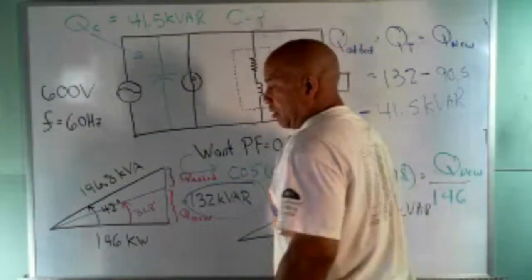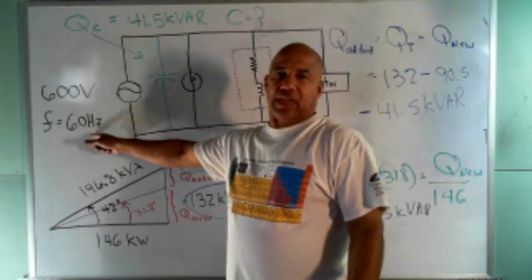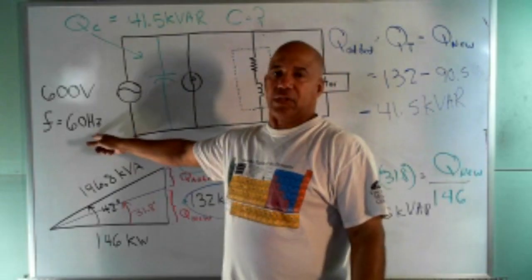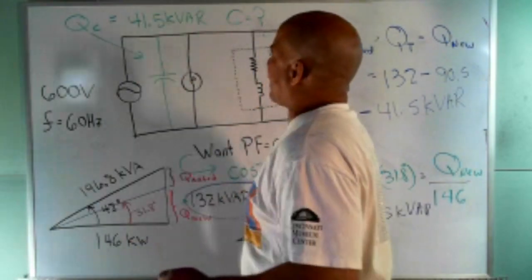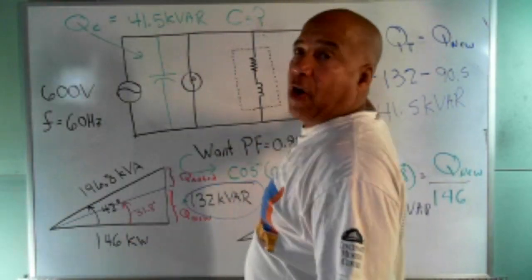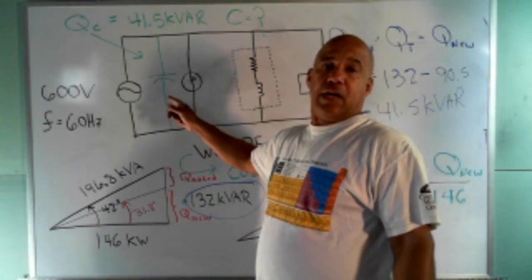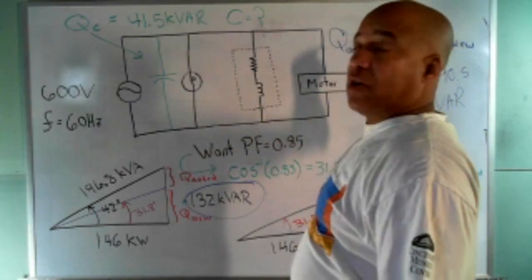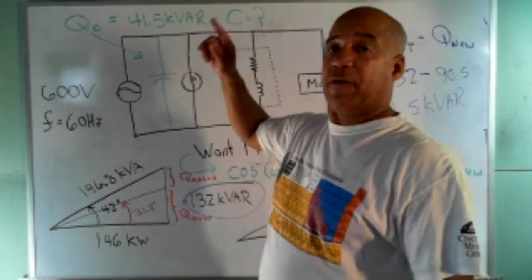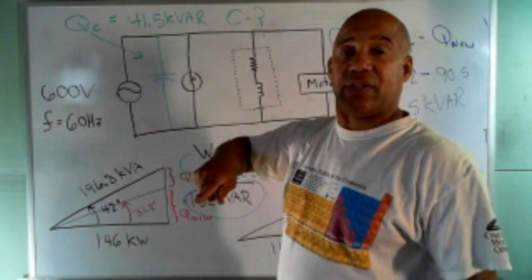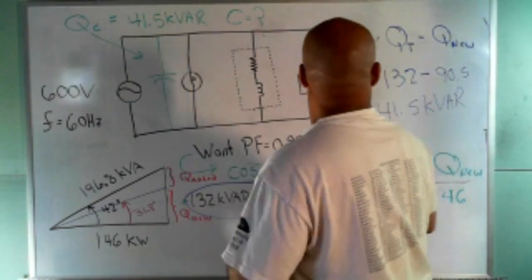Well, to get that, I got to do a couple things. They gave me the frequency there, so they didn't just put it there to be cute. They want me to use it. So if you think back, I got to some kind of way get from vars to microfarads. There's no direct link that I know of, but I can do it in two steps. I can go from vars to opposition, and then from opposition to microfarads if you remember your equations. So let's do it.